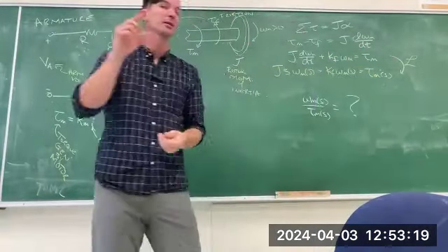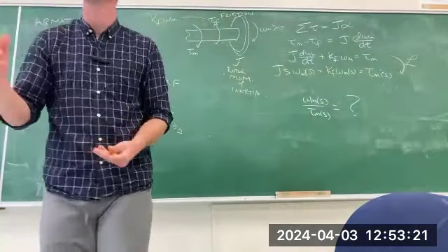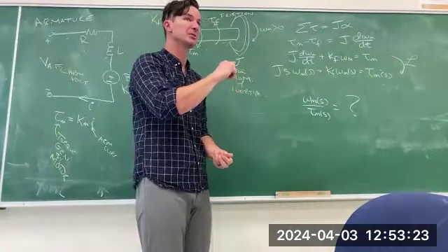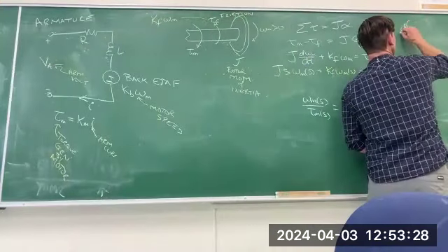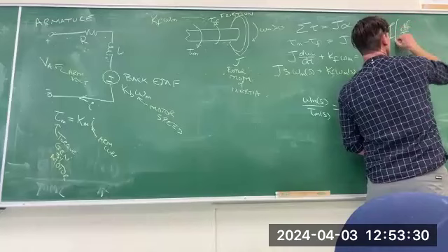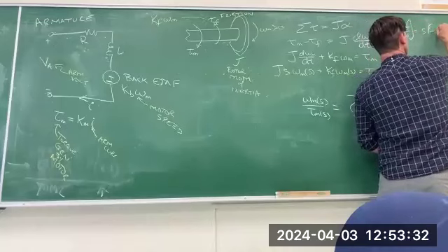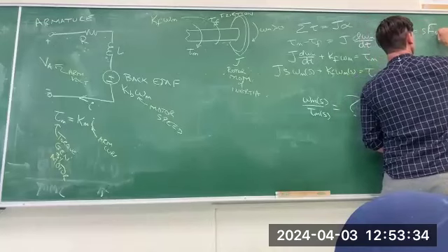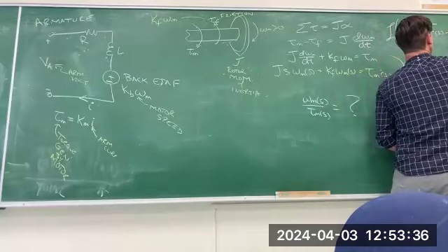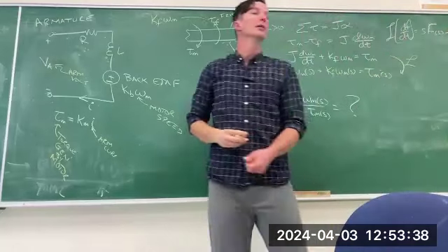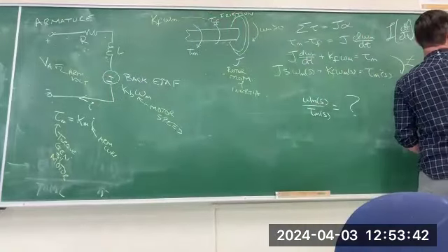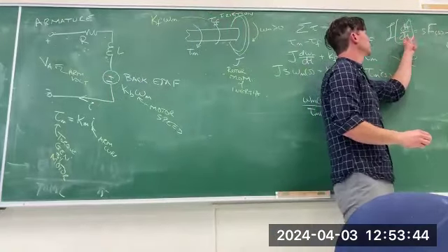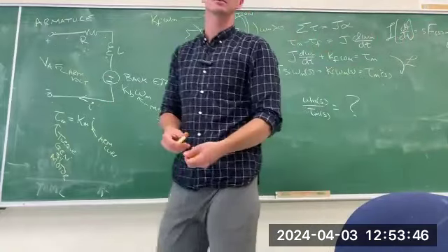And then what does Laplace do to differentiation? This is the property that you learned: df dt becomes s F of s minus f of 0. If we're after a transfer function, we're assuming 0 initial conditions. So a differentiation in time is a multiplication by s.